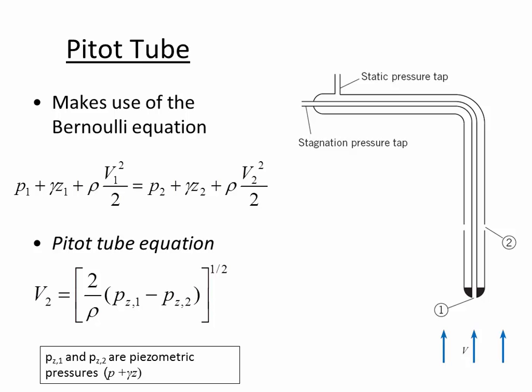The velocity that's going to intersect location 1 is going to cause a stagnation at 1. And so the pressure at 1 is going to be abnormally high. It's going to be higher than the surrounding atmospheric pressure because of that stagnation. All of the energy that existed as velocity is temporarily, and at just this location, being transformed into a small increase in pressure.